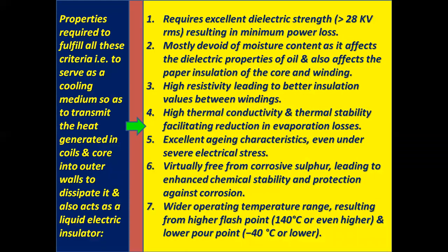Properties required of oil to fulfill all these criteria, that is, to serve as a cooling medium so as to transmit the heat generated in the coils and core to the outer walls to dissipate it, and also act as a liquid electric insulator. 1, it requires excellent dielectric strength, that is more than 28 kV RMS, resulting in minimum power loss.